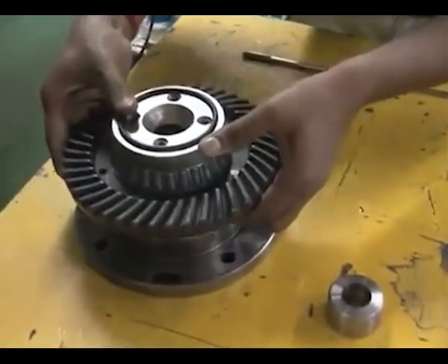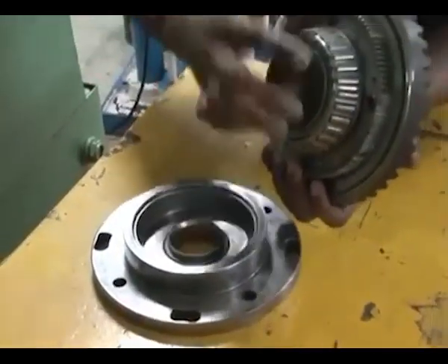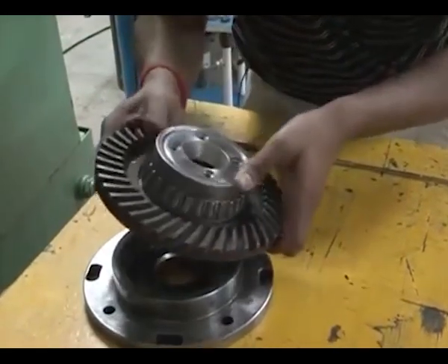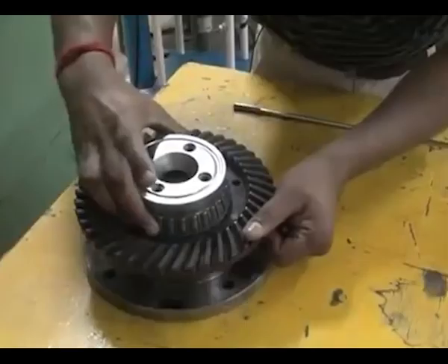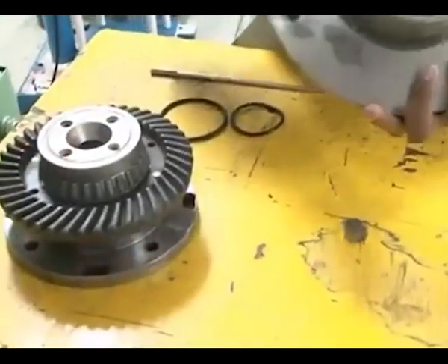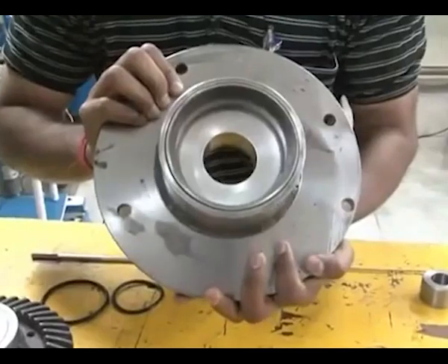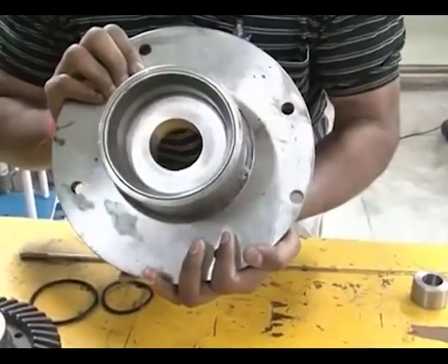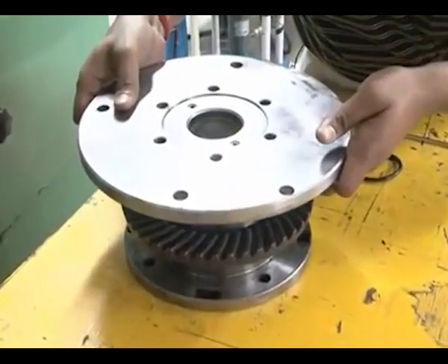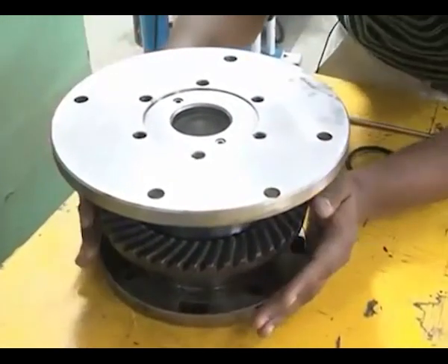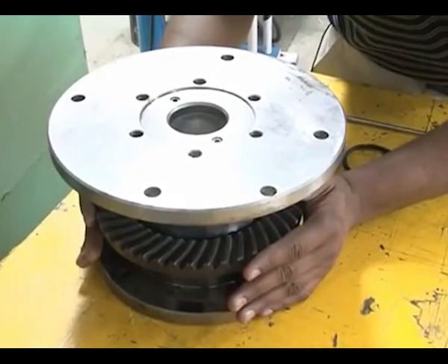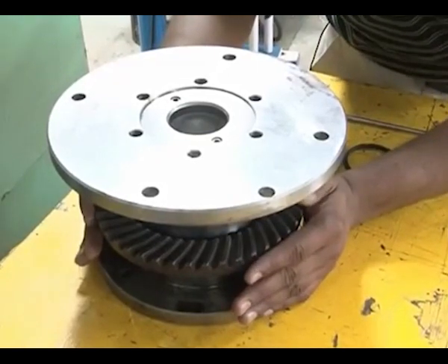We place this total system in the bottom plate. There are 2 ball bearings. This is one ball bearing and another one is the top ball bearing, in order to give free motion to the workpiece. This is the top plate to cover the complete tooling, and this will go and sit like this. This is called the complete rotational tooling for the universal rotational abrasive flow finishing process.